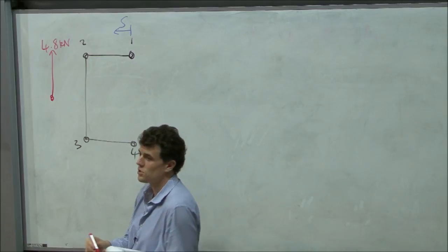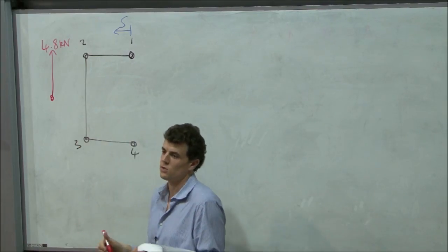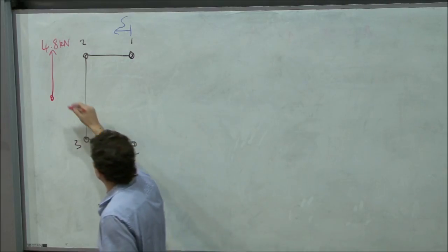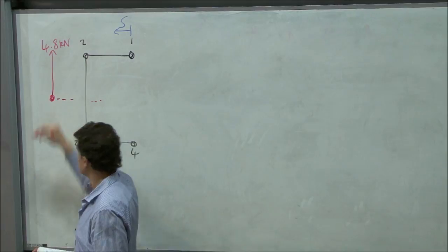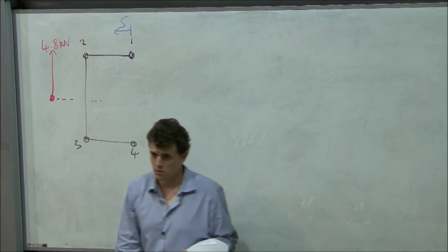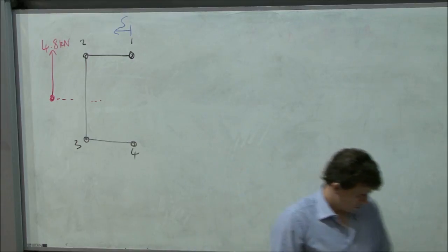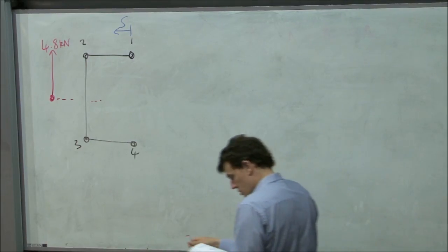Yeah, I'm applying it at the shear centre. Because if I don't apply it at the shear centre, I induce all sorts of weird twist in this that I don't want to calculate. So we always, for open sections, or nearly always, assume it's at the shear centre. And the last thing we need are some dimensions.